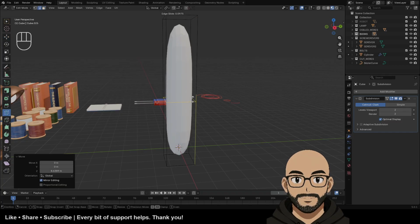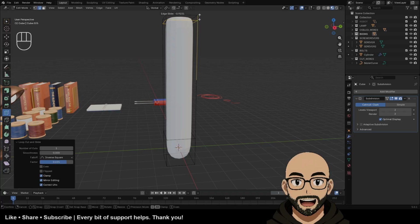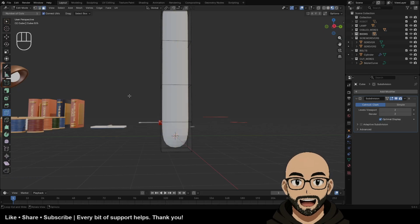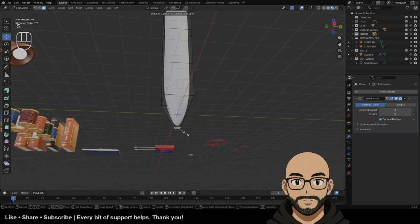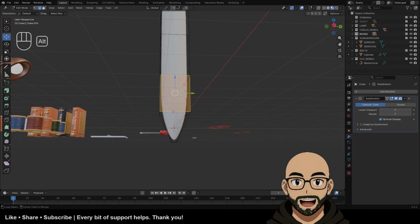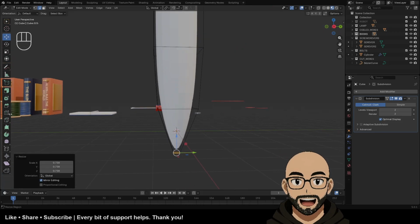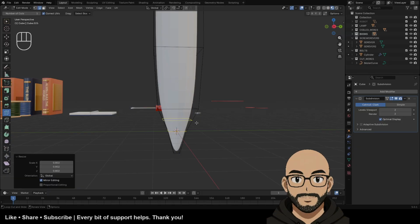We're going to add some edge loops. And you can see it's pretty rounded. Surprisingly, which is quite cool. Alright, so now we've got a pencil almost. This bottom face we want to select and just taper it. And you can of course select this edge loop here and taper it in too. And then I'm going to add an additional loop in here, and this sharpens this. There we go.